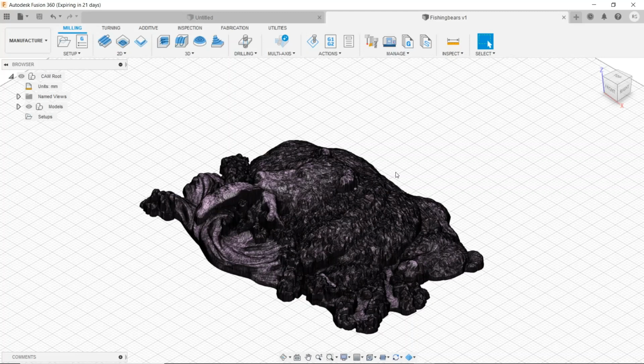Because if you cut this with a small bit, say a 1/8 bit or even smaller, this is going to take hours and hours to cut. Even as small as being a 3x4, because of the layering that you have to do in order to whittle this down to a 1/2 inch, because you can only take up so much for each cut.